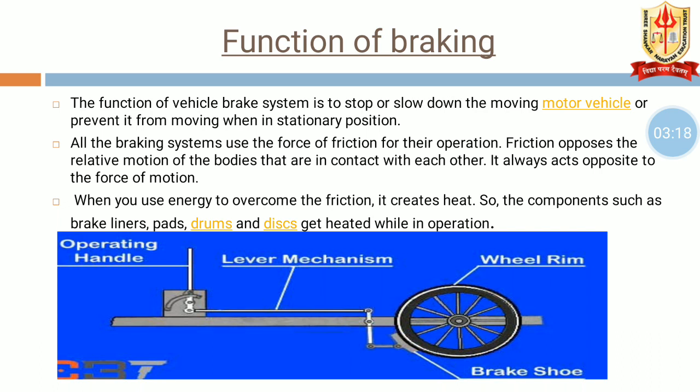So that's why we require brakes: for deceleration when it is operational, for the complete stopping, and to hold it when it is in parking. All the braking systems use the force of friction for their operation. So the basic principle of working is friction. The brake works only on frictional force. Friction opposes the relative motion of the bodies that are in contact with each other. It always acts opposite to the force of motion.